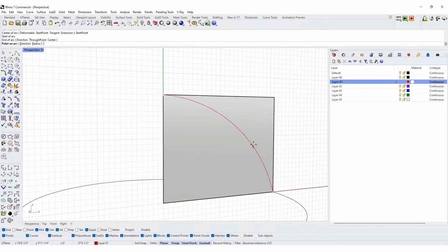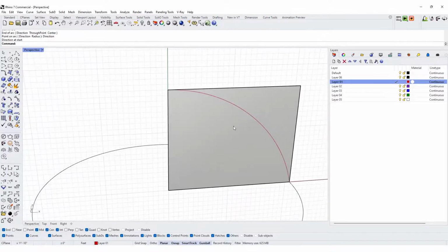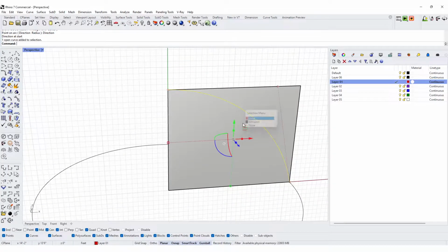And now we can pick the slope. You know, we can go like toroidal field kind of thing, or we can go more like a pointed dome. But if we want it to be more of a smooth, almost perfect dome, then we can pick direction, and I can go this way. Holding down shift, I can snap to my ortho this way. Now when you click, we've created this curved section.